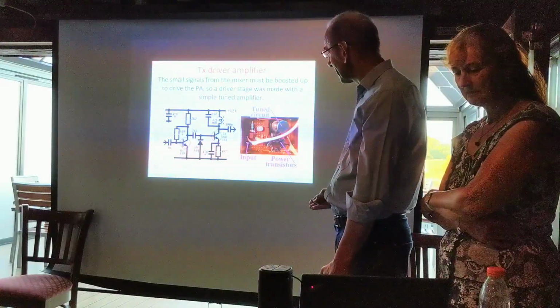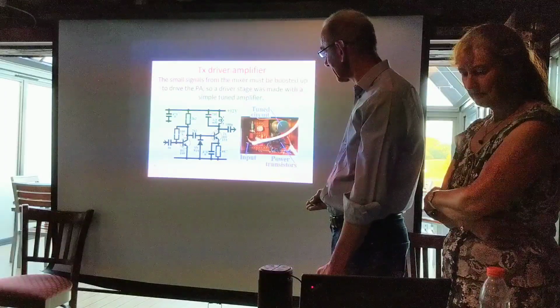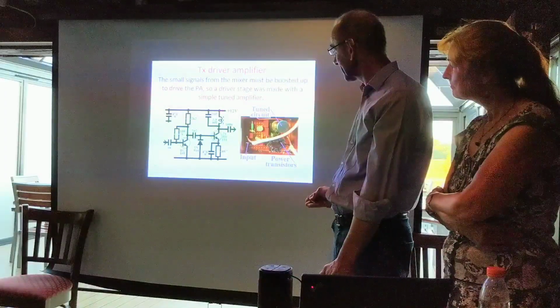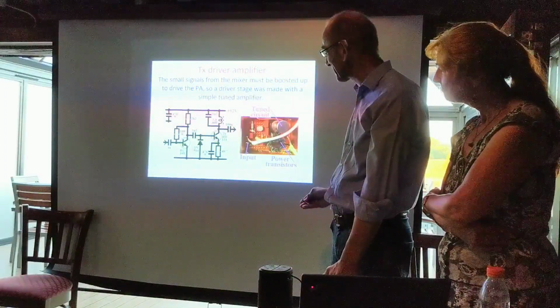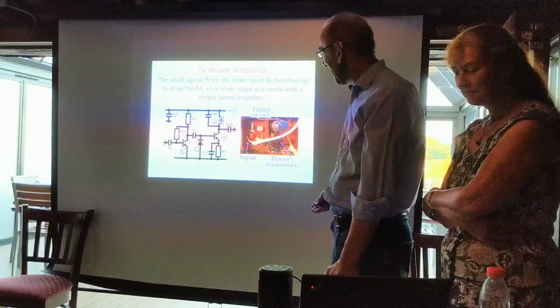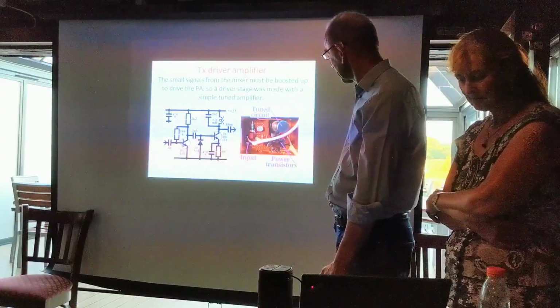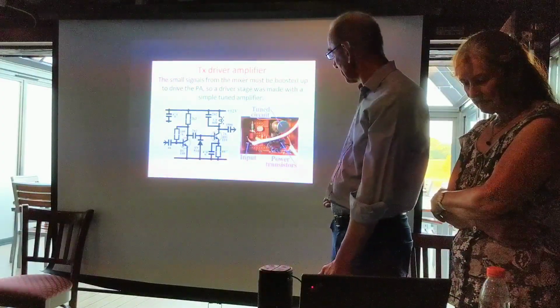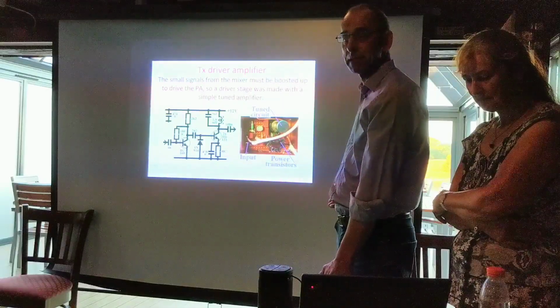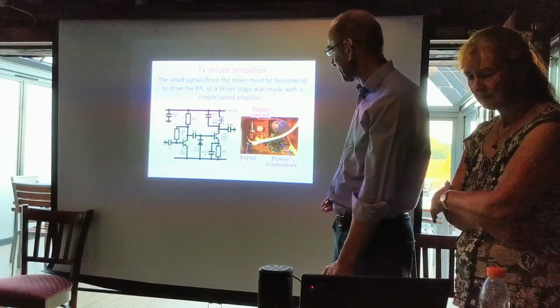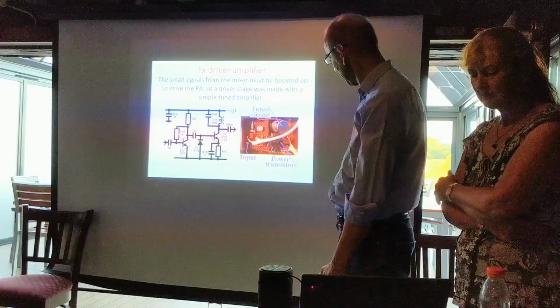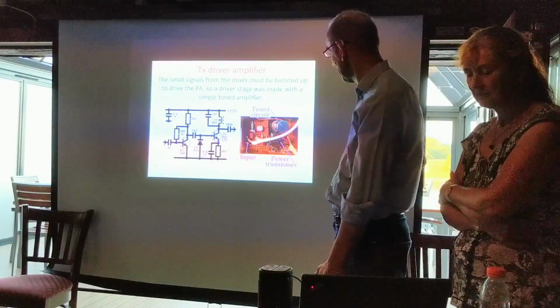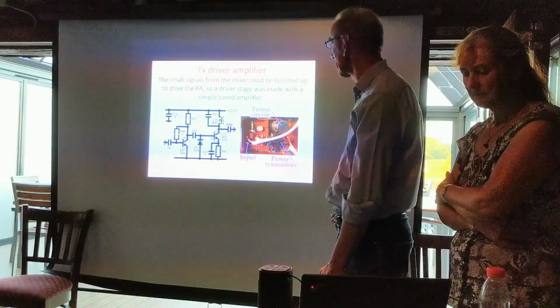And here we have a tuned amplifier. Basically, there it is again, that little parallel tune circuit in the collector. And I've actually taken what I found in the junk box, got a bit hot, so I put 2 of them together. So it's actually 2 transistors wired in parallel with each other, and a big heat sink to dissipate any power. And there's the tuned circuit.